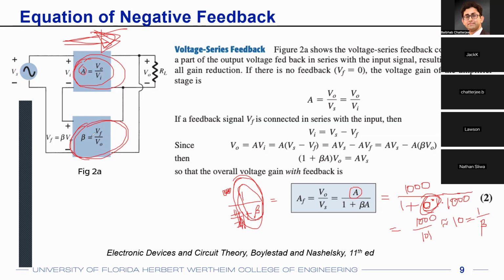On the other hand, for your beta network, whether you do it in the lab within the air-conditioned system or if you do it outside in the heat, you'll see that the beta network, your problems 1, 2, and 3 in your homework 1, will have very similar results. So the fluctuations in a passive beta network are much lower than the fluctuations in the active network created with an active gain element A. And using negative feedback, you can stabilize the gain. So your A over 1 plus A beta, if your A is very large, eventually boils down to 1 over beta, and that 1 over beta is a very stable number. That's the reason why people go for this negative feedback system.